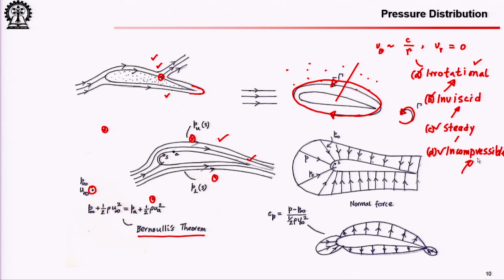But in the region below Mach number 0.3, as I said, your changes in velocity are not enough to cause enough changes in pressure to cause enough changes in density. So, that sequence you have to keep in mind. That is why below Mach 0.3 flow can be treated as constant density, so uniform and steady in terms of density.